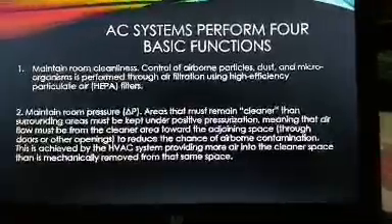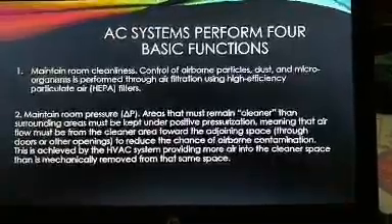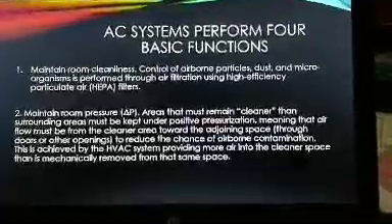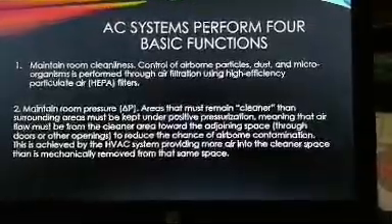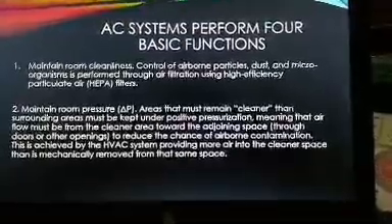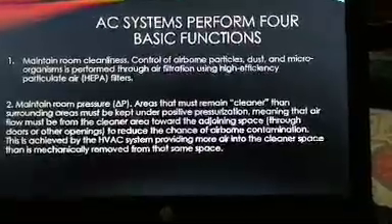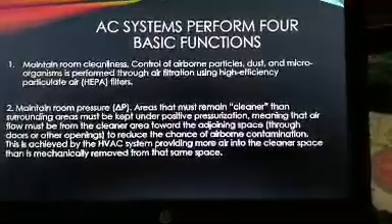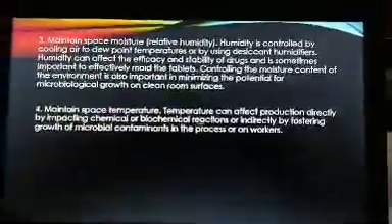Areas that must remain cleaner than surrounding areas must be kept under positive pressurization, meaning that air must flow from the cleaner area toward the adjoining space through doors or other openings to reduce the chance of airborne contamination. This is achieved by the HVAC system providing more air into the cleaner space that is then mechanically removed from the surrounding space.